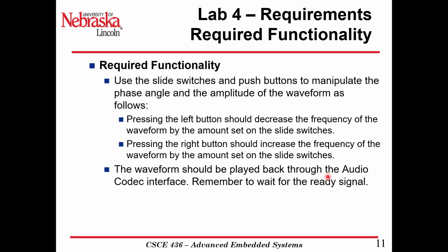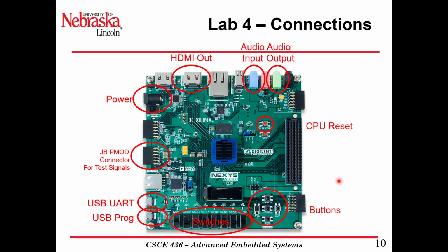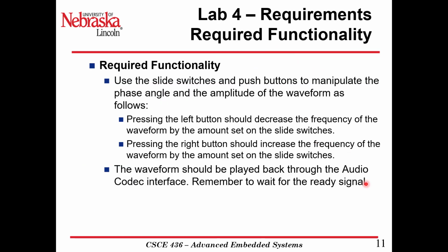The waveform will be played back through the audio codec interface to the output channel. And you're going to wait for that ready signal to give it a new word of data, 18 bits or 16 bits plus 2 bits of 0 at the end.